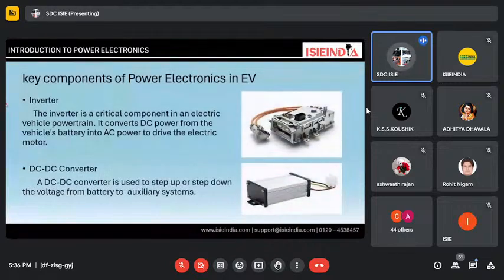We see a lot of components, but some have power electronic components inside them, like a small SCR, transistor, and rectifier. I will not go through all of them, but I will explain some of the components. Like the inverter, where we use an inverter with the DC power supply, for the driver circuit to run the motor and the peripheral devices. This is the efficient part of the EV powertrain, where we transmit the power from one part to another to propel the wheel. These are parts of the inverter, where we change DC into AC form